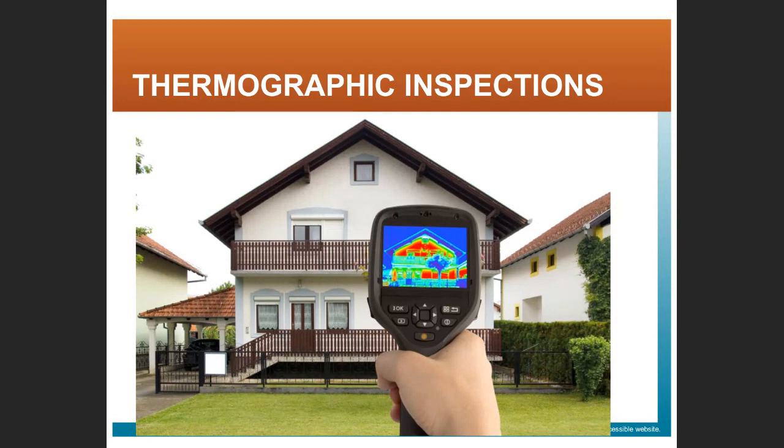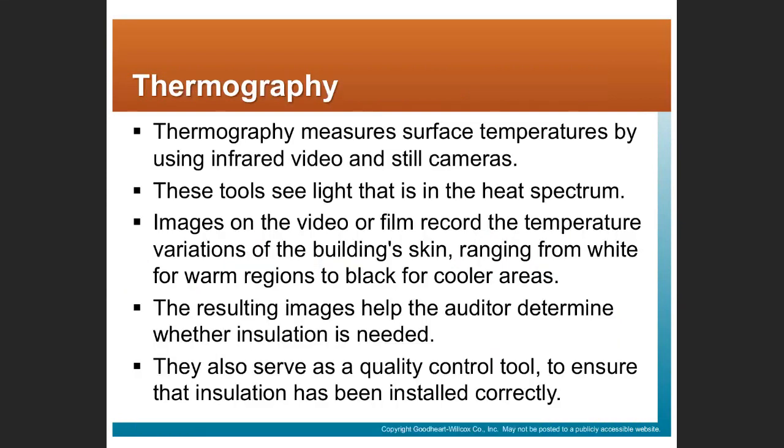It might also be a tool that a contractor or general contractor might use to check on the work of their insulation subcontractor, or a tool that the architect might use to check to see if the construction team has delivered on the quality of construction and the detailing that was specified. Right? You see thermography as a quality control tool to ensure that insulation has been installed correctly.